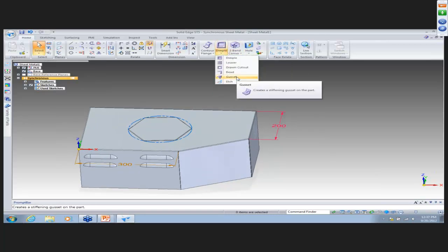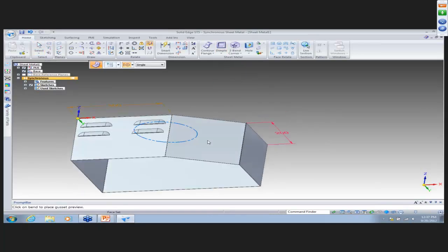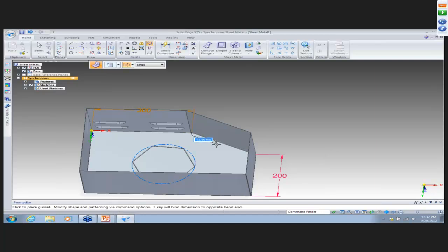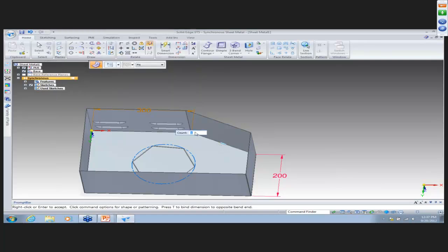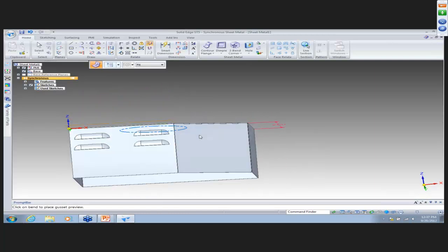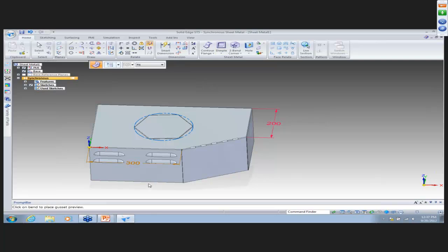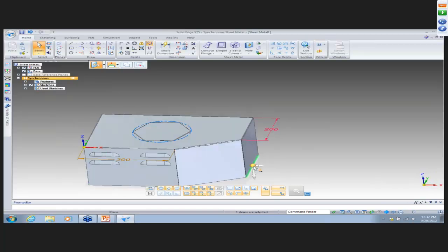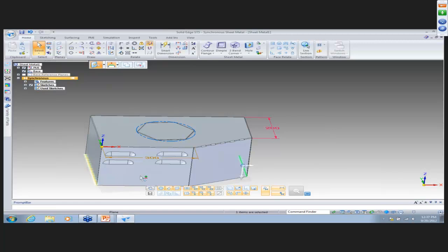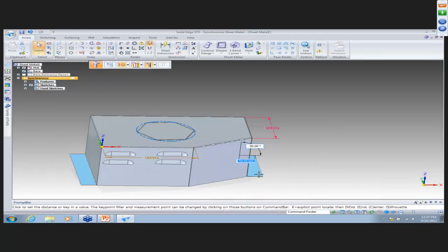And we'll also look in here on the underside. We'll put some gussets in there just so we have a couple more features. We'll also pull out on each side some flanges that we would use for mounting that we can put some holes in. That way you can see how the holes behave in the flat pattern.